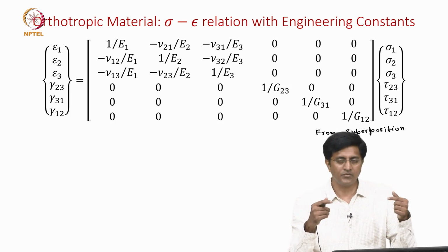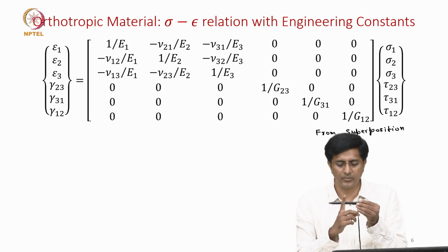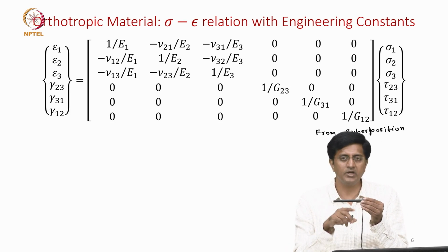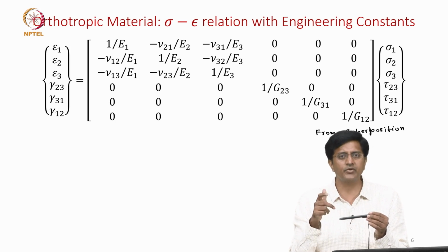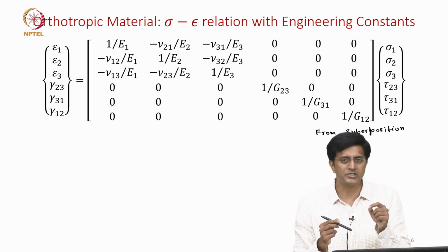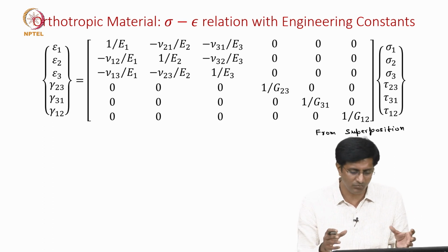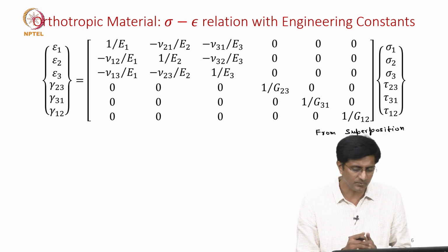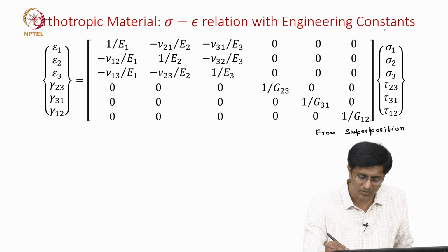meaning that in the first experiment it is only uniaxial in direction 1, in the second experiment it is uniaxial in direction 2. Similarly, I could have done another experiment uniaxial in direction 3, and the three different experiments we have done with one shear stress in each experiment. So, if we bring all those 6 experiments together and then we replace the compliance terms, now we get this compliance matrix, because we have said that strain is written as the compliance matrix S times the stress.